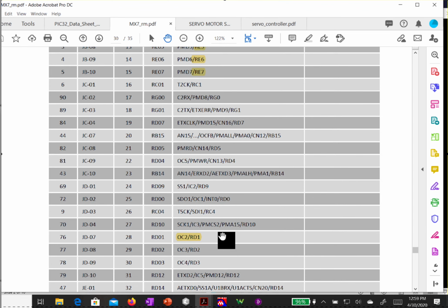So we see those are shared. And in fact, I'm using this port as my timer output, so I don't have to change my scope, so I can give you the demonstration. But if I wanted to use both of those, I would have to make a decision which one am I going to use, because I can't use them both simultaneously. So this is why I'm changing demos, because I have to use one or the other, which is the reality of when we use these microcontrollers.